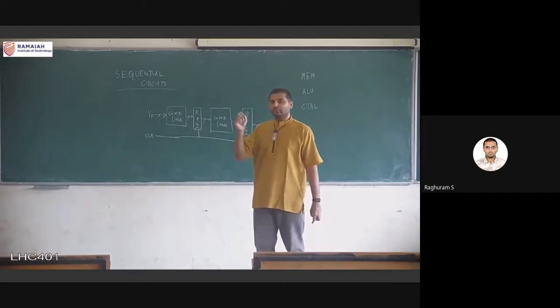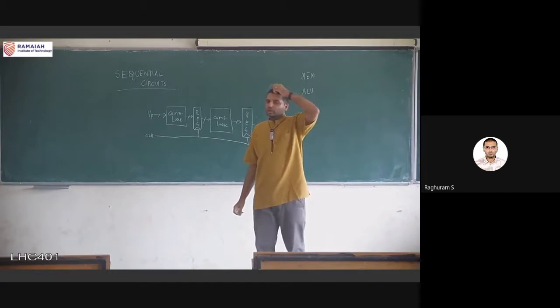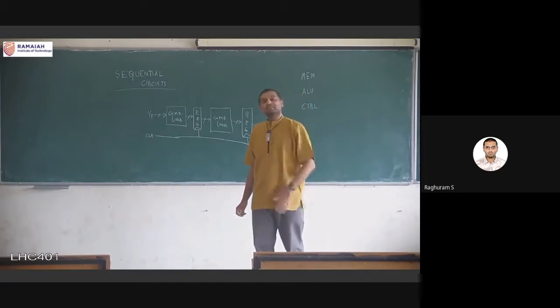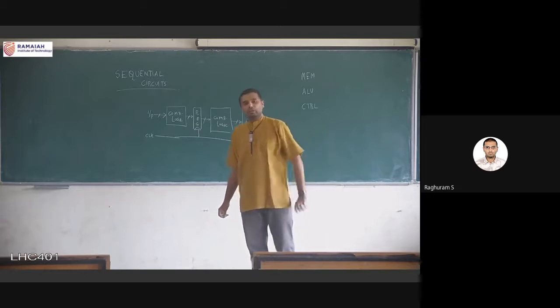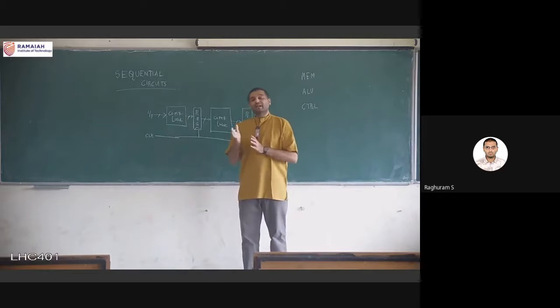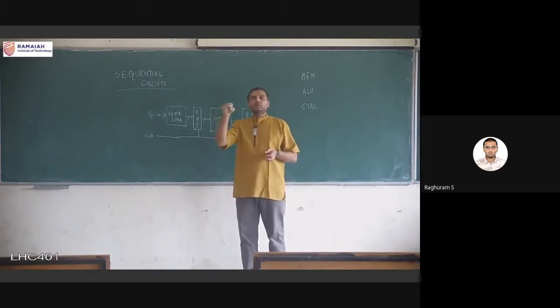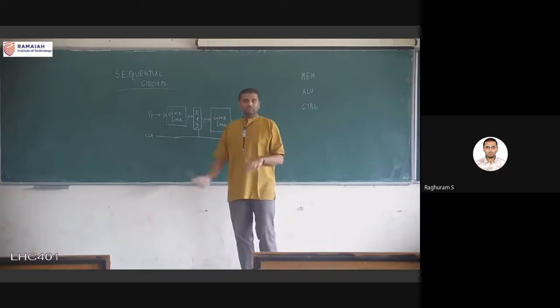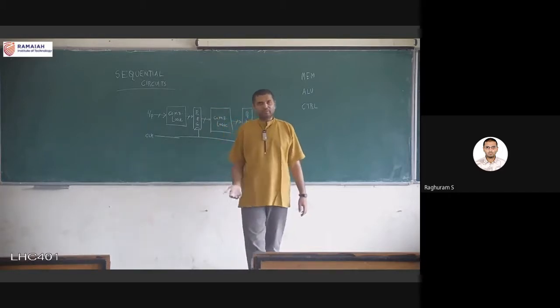If you remember when we talked about the structured design strategies, try to make all the signals temporally local. Temporally local means all the signals should be ready at about the same time. When is that time? When the edge of the clock is coming. So this basically is an example of that.